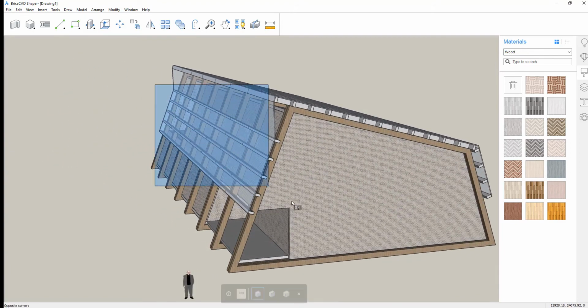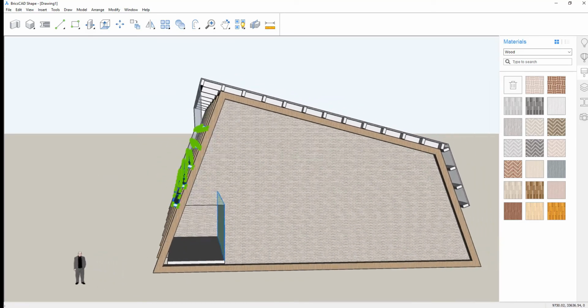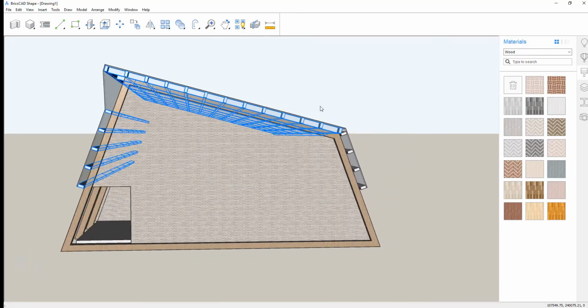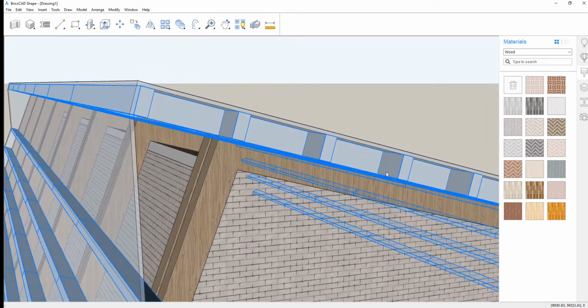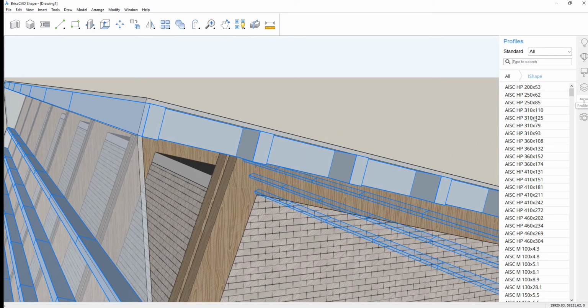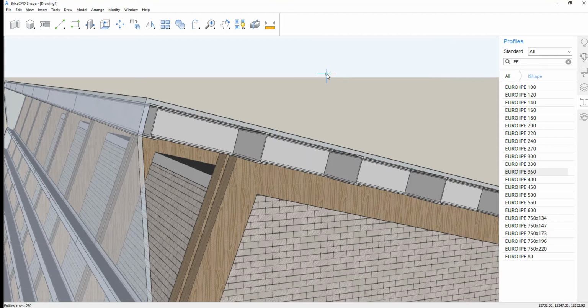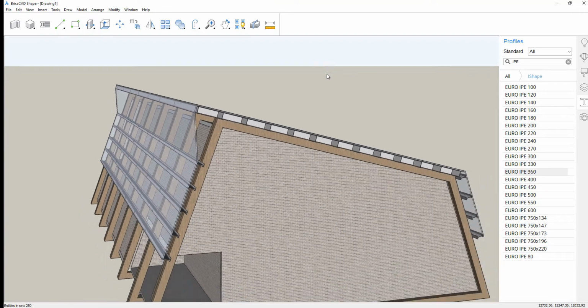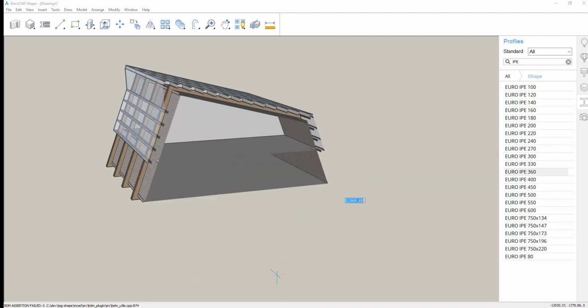Awesome. Next step, select the beams. We want to change the profile from a rectangle to a standard structural I-beam. We'll search for the range of shapes we want to use and then simply drag and drop that shape onto the beam elements, and they convert to I-beam profiles that are actually stored in the database. So that data will move to BIM very quickly.